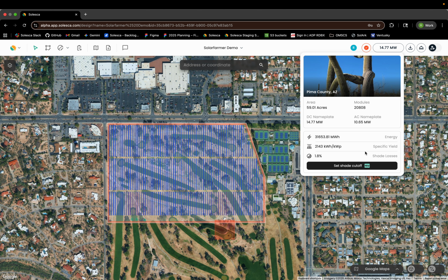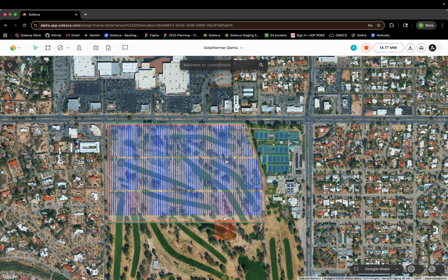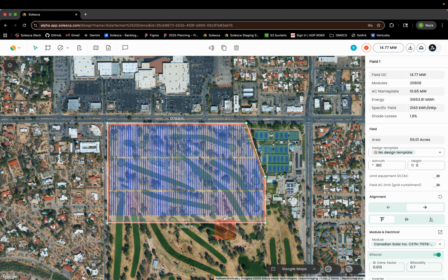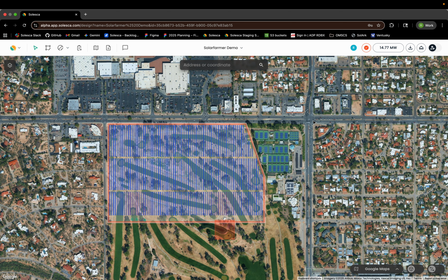Taking a step back, for modeling, there's really three pillars of the model. There's the model itself, so what engine is doing all these calculations. Then there are the assumptions that you feed to the model, so DC wiring loss, AC wiring loss, transmission factors, bifacial assumptions. And then the layout itself. So that layout matters. Your row spacing matters, your type matters, fixed tilt or single axis tracker, your tilt matters. Those three pillars are fed together and encompass this energy model.